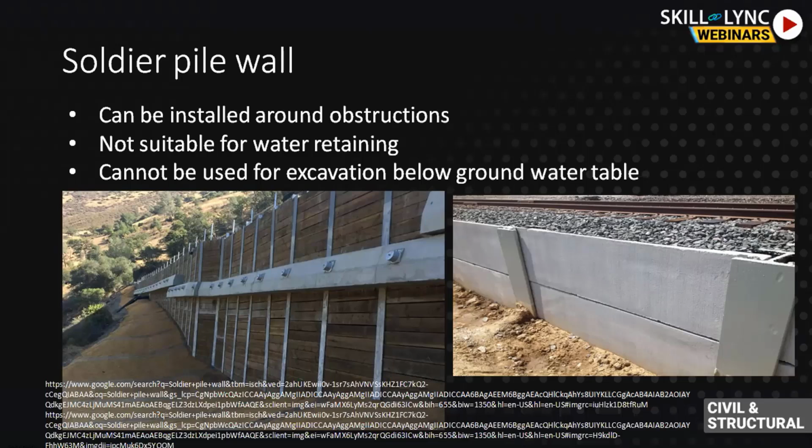There can be potential ground movements in drained conditions. There can be safety issues with ground instability, with clay falling through the gaps. Sometimes the lagging can fall down when it is not fixed properly.